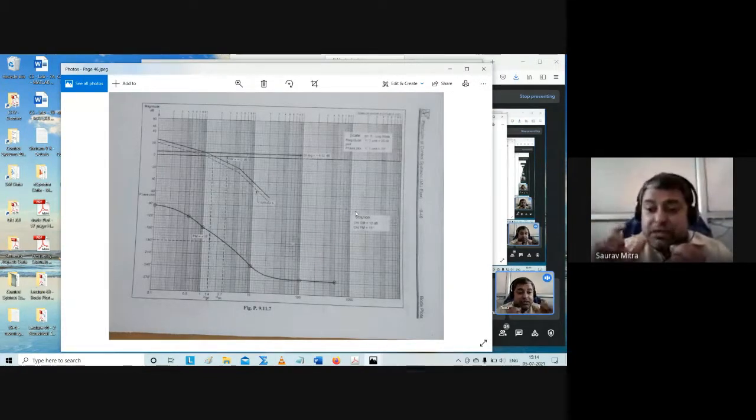And what is the best sweet spot? What is the best input frequency for both gain and phase to be stable? The answer is in between omega GC and omega PC. That means you input any frequency between 1.4 radian per second and 2.7 radian per second. As per our knowledge, this is the best frequency range which will be stably amplified, or stably processed, by the system.